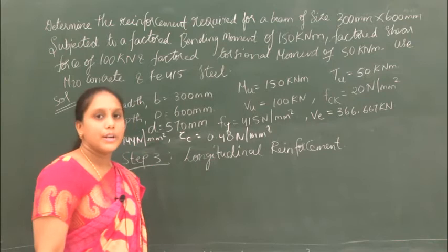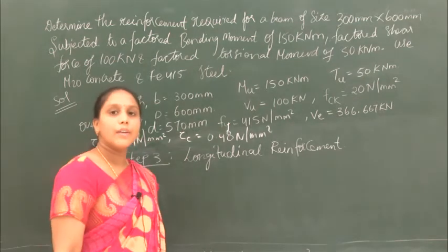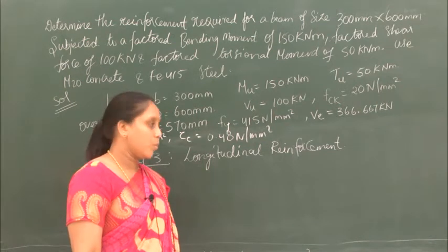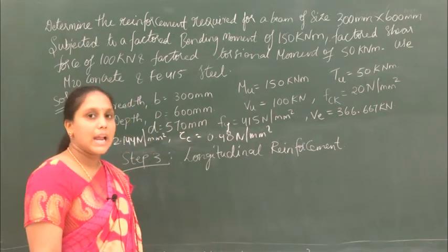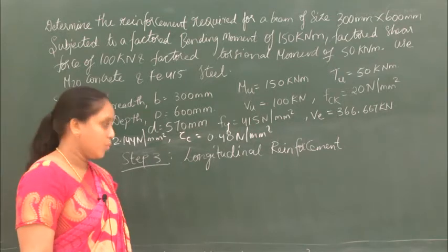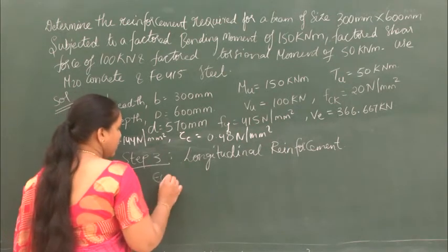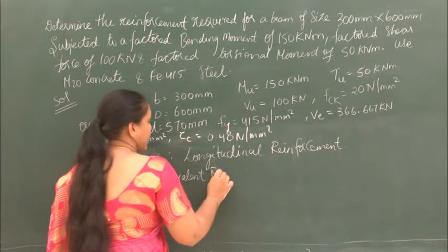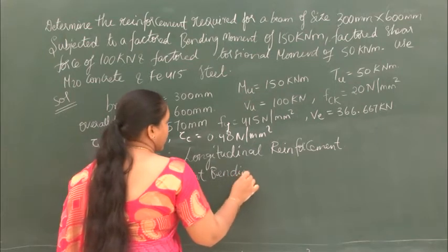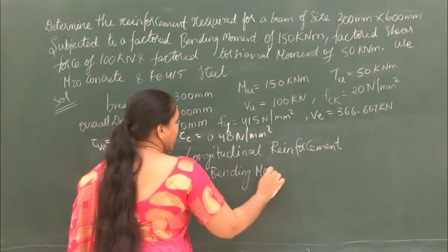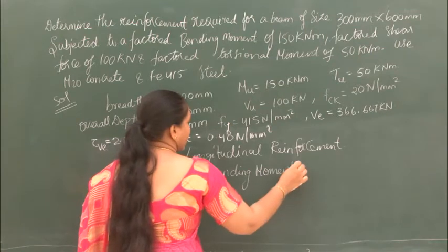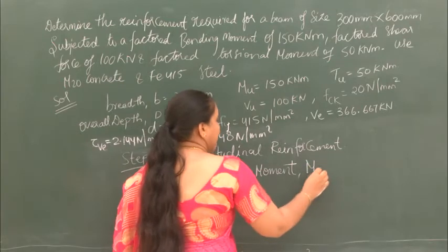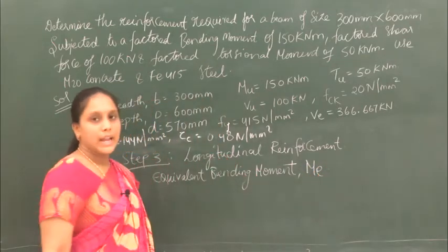So to provide the longitudinal reinforcement, first what we have to do? We have to calculate the equivalent bending moment. So first what we will do is we will calculate the equivalent bending moment ME.